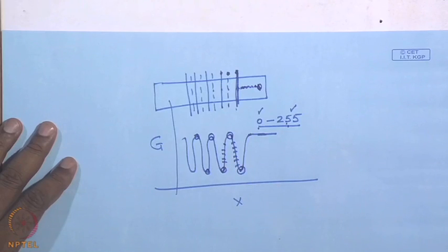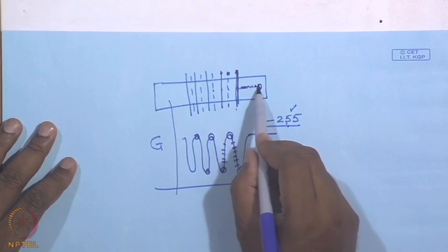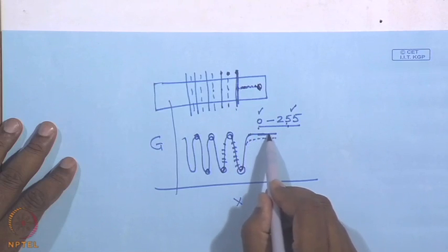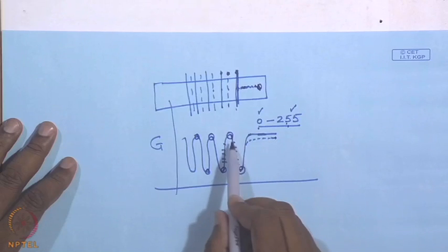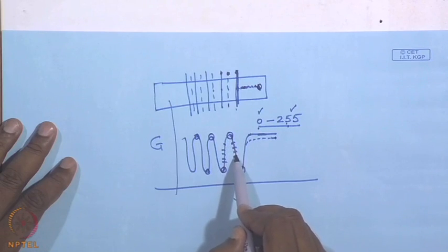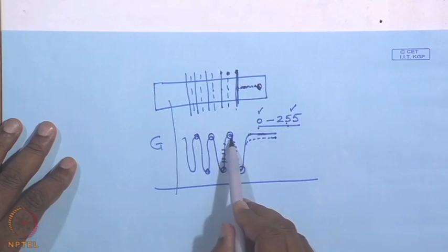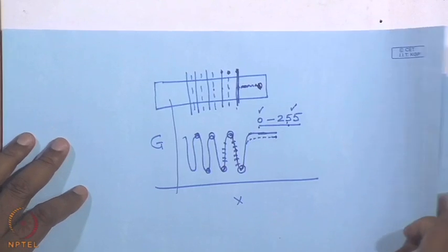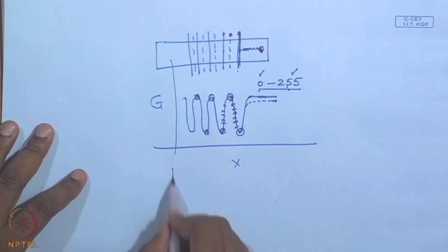And if the adsorbed film thickness is more, then it is going to start from here. The reflectivity of the film covered surface will be even less. So, finding out the gray values of every pixel, that means finding out the reflectivity of every point, it is now possible to convert the pixel data into film thickness data.